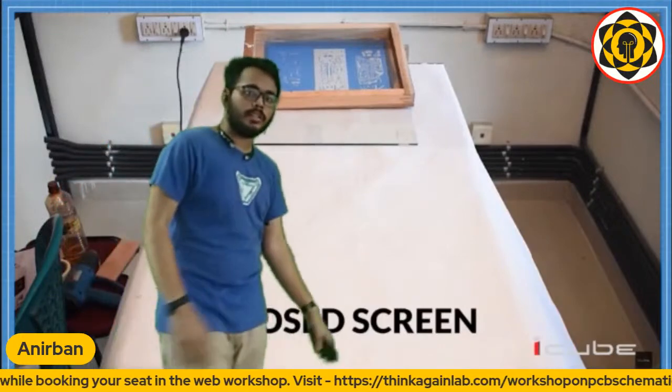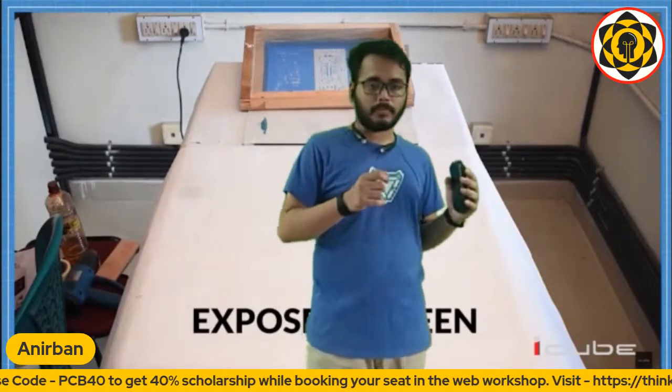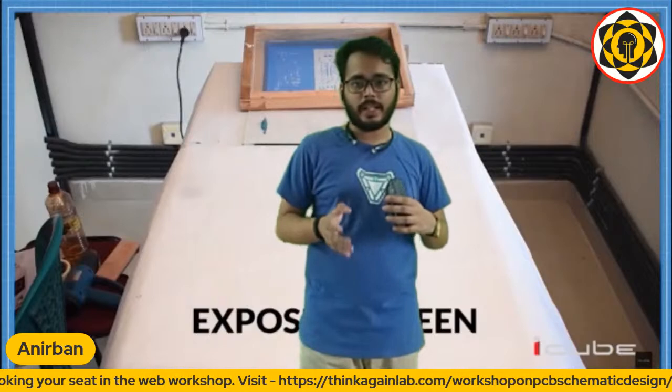But if you don't have a screen and you need to do a one-time experiment, you don't need to make this expensive screen. All you can do is buy some transfer paper. You will get it in any stationery store. Just go there and say I need some transfer paper. It looks like normal paper, but it's a bit different because the ink on it dissolves when heated. So buy some transfer paper sheets. Go to a shop that has a laser printer. Inkjet printers won't work. Get the design printed from a PDF, then press the design on the copper board and just heat it with an iron.